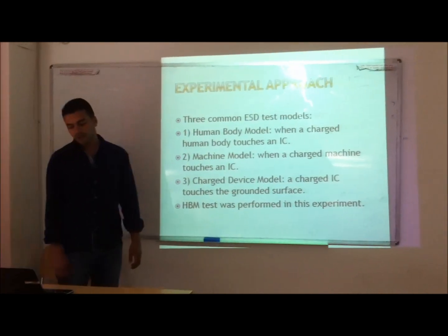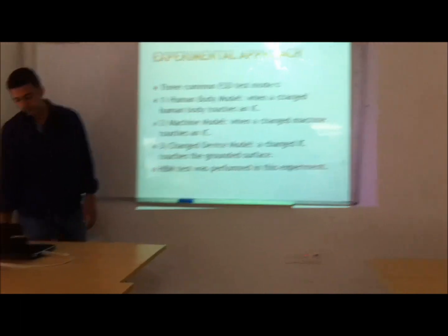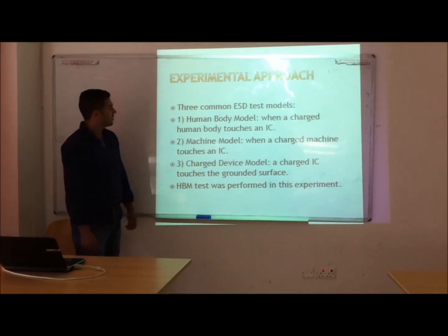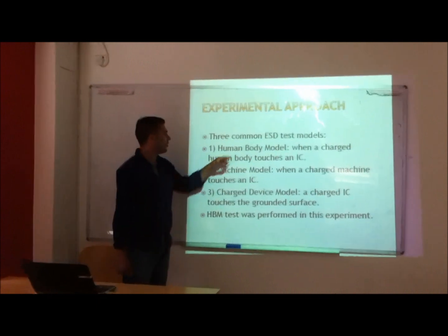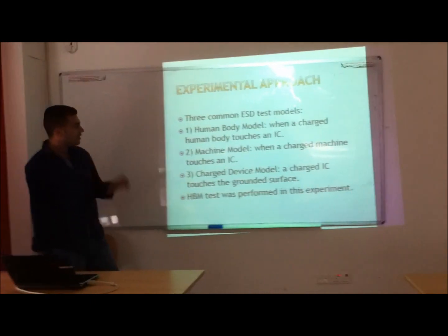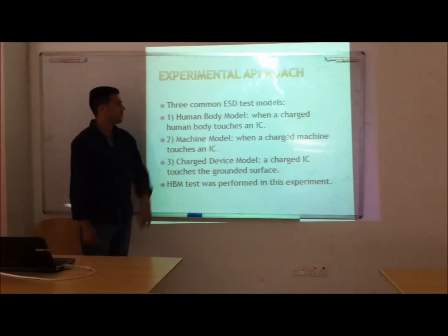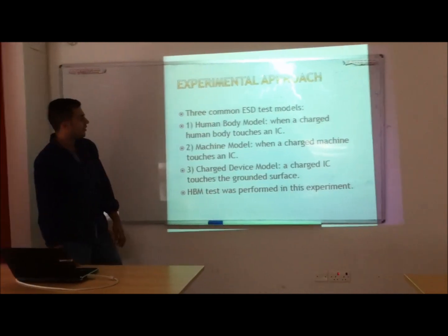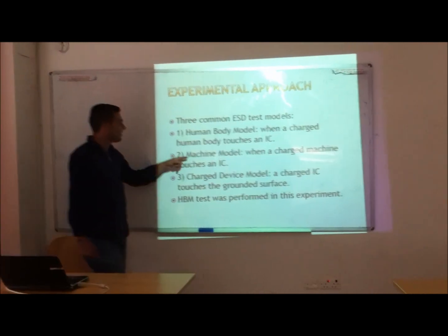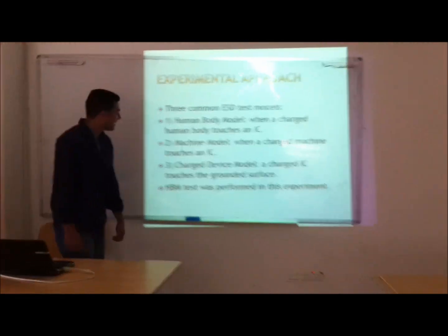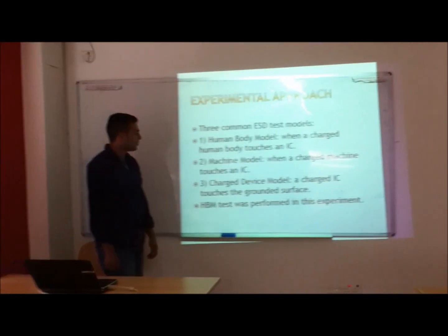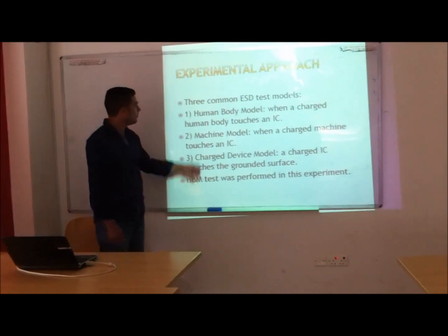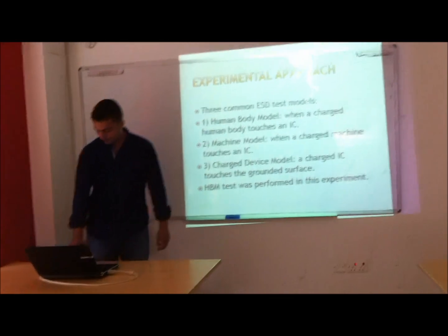There are 3 common electrostatic discharge test models. First, HBM or human body model, when a charged human body touches an IC. So when a human touches the electrical component, there will be electrostatic discharge. Then the machine model, when a charged machine touches an IC. And the charged device model, when a charged IC touches a grounded surface. In this case study, the HBM or human body model was performed in this experiment.